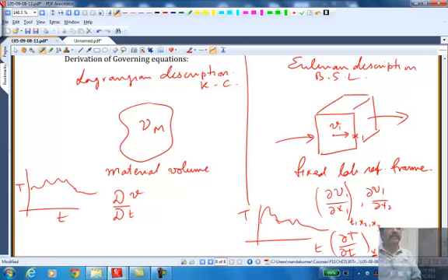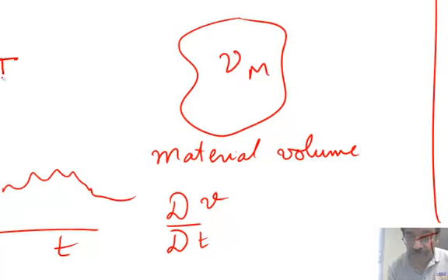On the right hand side, I measured the temperature at a particular fixed point. That is Eulerian. In here, I have a derivative of temperature with respect to time, but that contains information about how fast the temperature is changing, not only with time but with position, because he is moving through the position. But it is the same material volume, meaning it's him that I'm following, or the thermocouple at his hand. So that temperature is going to be a function of the position and the time.